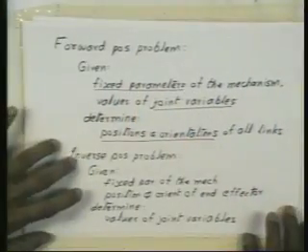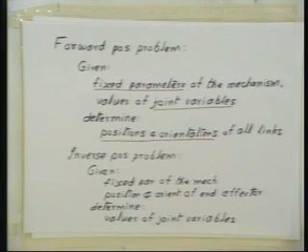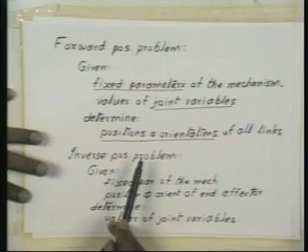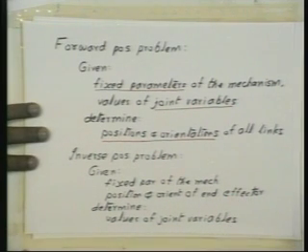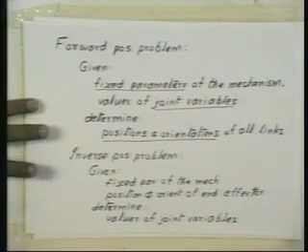So now, we had defined the problem of forward and inverse kinematics, and we have now seen two planar mechanisms which are fairly easily solved, and one spatial mechanism which is easy if we set up the reference frame in a particular fashion. Now we need to look at spatial manipulators in their generality, and in order to do that, we need to define some of these things which were left undefined. So what we will first take up is the idea of position and orientation. How do we define position and orientation of rigid bodies? You have done a bit of this when you did engineering mechanics or a corresponding physics course, but we will do it formally now.